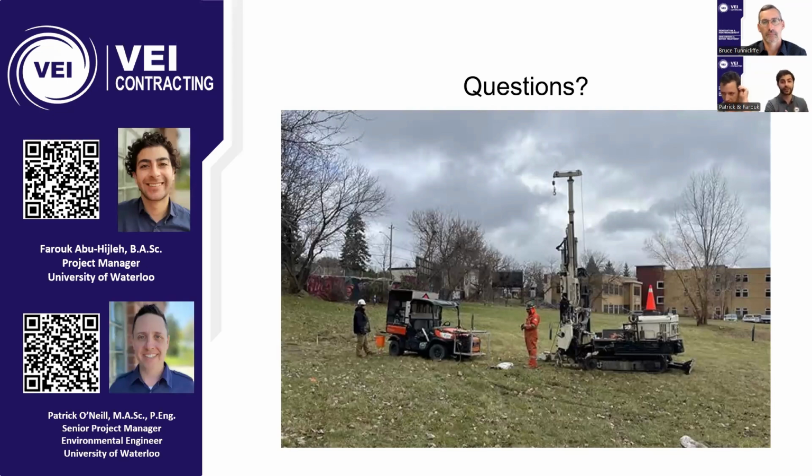So I build a system that can do up to 2 million liters a day. Well, then when we get to site and we strip away all those factors of safety, I have a system that's actually running at 500,000 liters a day. So a quarter of that flow, but I built a system that's 3 times the cost for the client. So it's something to keep in mind why it's important to get accurate values.